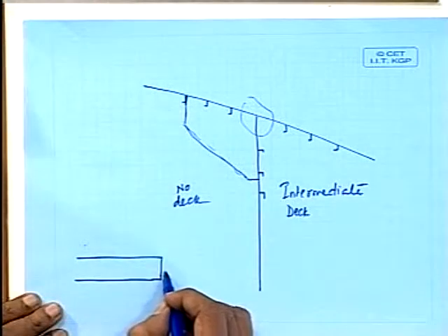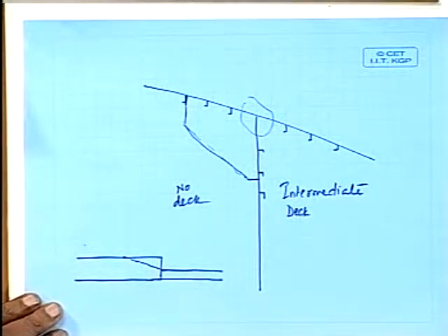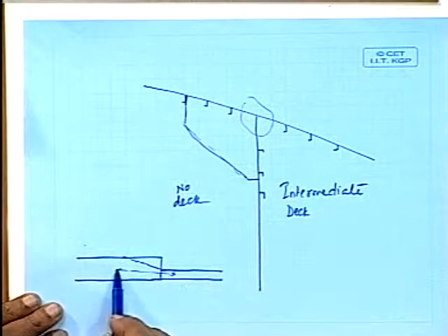Wherever you are designing structures, some plates you want to make thick, and some plates where loads are less you want to make thin. So can you weld a really thick quantity of material to a really small quantity of material and call it continuous and aligned? The answer is no. There must be a gradual change in the material quantity as well. That is, if you have got a 20 mm plate and you got a 10 mm plate, then there must be a portion where this 20 mm plate will be cut like this, so that the change is gradual over the distance.